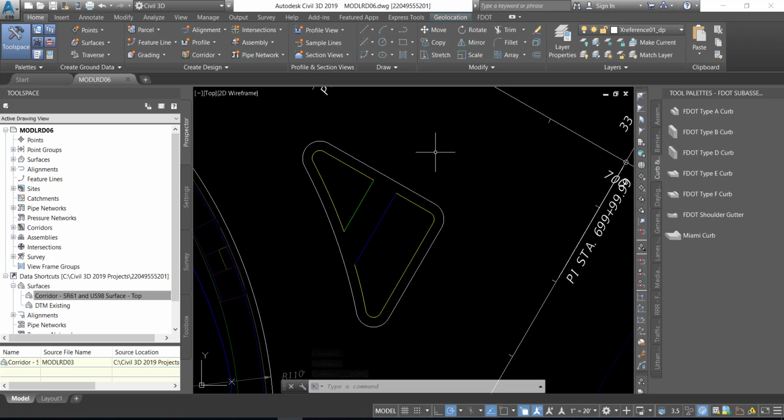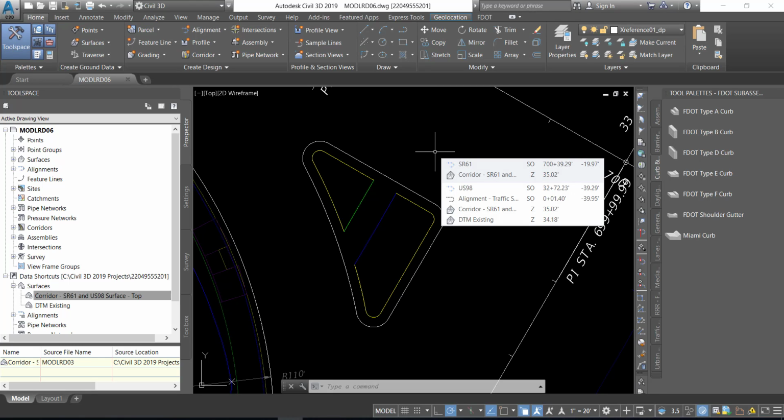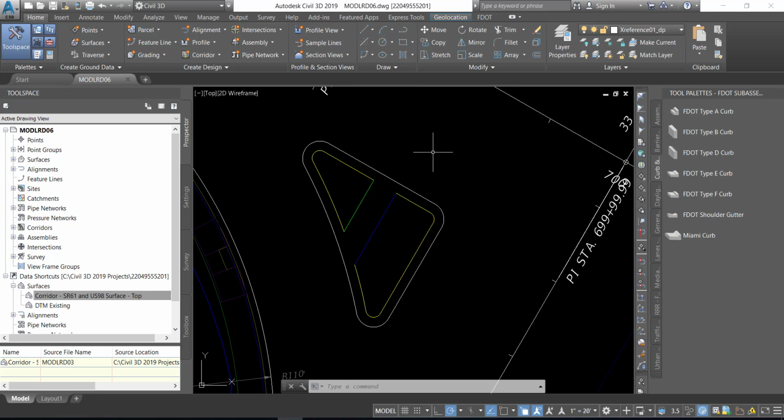Exercise 9.4. Manage the attached external reference files, otherwise known as XREFs. You will unload the DSGN drawing as it no longer needs to be displayed underneath the traffic island 2D geometry that you just inserted using the copy command.